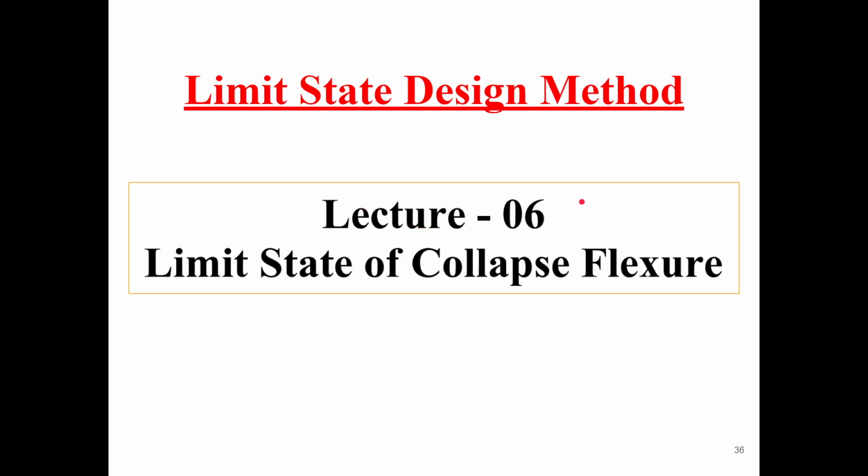So the main limit states. In the limit state design method, basically there are two: one is strength and one is serviceability. Under strength, there are basically four limit states: axial tension compression, shear, flexure, and torsion. And for serviceability, those are deflection and cracking.